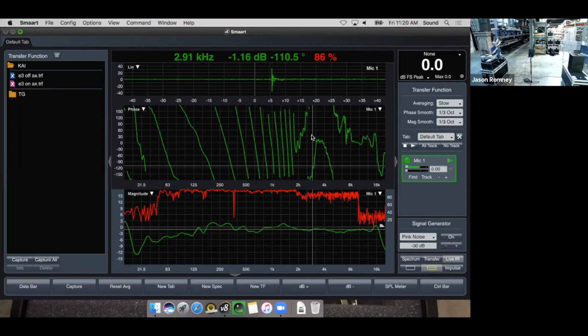Then it gets into the loudspeaker. The loudspeaker will have a certain amount of timing issues because of just the way the drivers move. The drivers are not going to move perfectly synchronously for every single frequency. Each frequency will be kind of pulsating at a slightly different phase just because of the mechanics of the driver, right? That's just how that works. Strictly speaking, that's not a time problem. That's just a mechanical problem of how the drivers oscillate, and they just oscillate frequencies at slightly different phases.